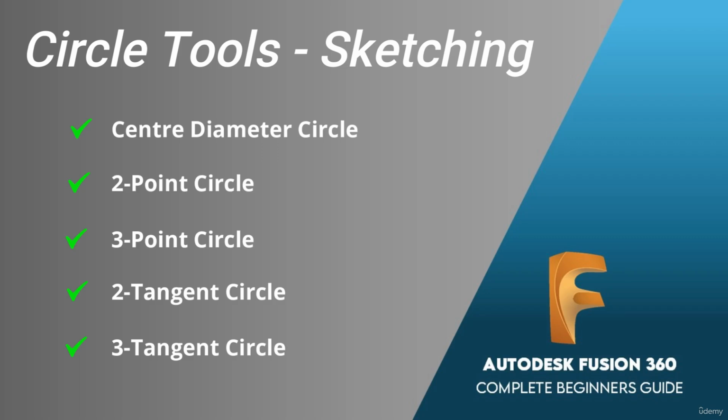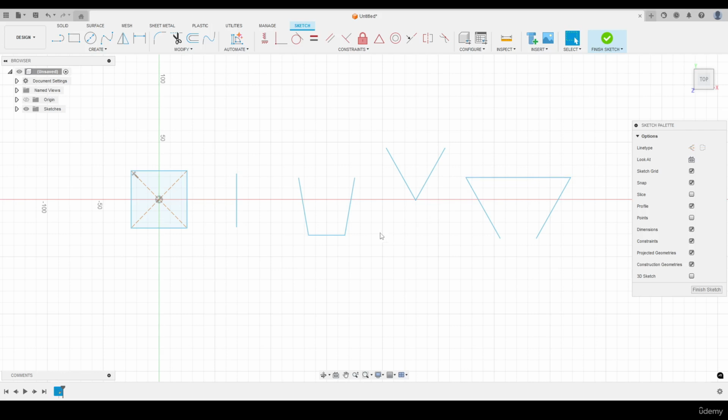In this lecture, we will learn about the functions of the 5 types of circle tools, and I'll demonstrate each one of these. So these are the center diameter circle. We've then got the 2-point circle, 3-point circle, and then we've got the 2 tangent and the 3 tangent circle as well. So I've opened up Fusion, I've started a new part, and as you can see here, I've input some geometries already. That's going to help me to demonstrate the functions behind each of these circle tools.